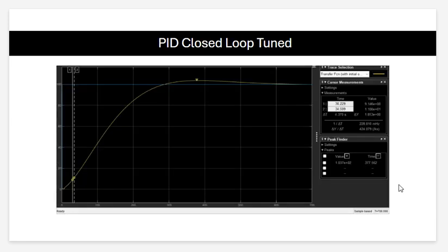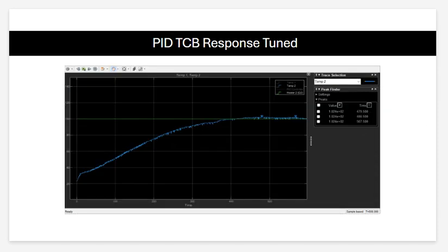And once we closed loop it, after tuning the PID gains, the closed loop response improves dramatically, overshoot is reduced, and the response becomes smoother, and the settling time shortens. The tuned controller stabilizes the system faster and tracks its set point much more accurately. And after we've tuned it, we can see that our results are somewhat the same.